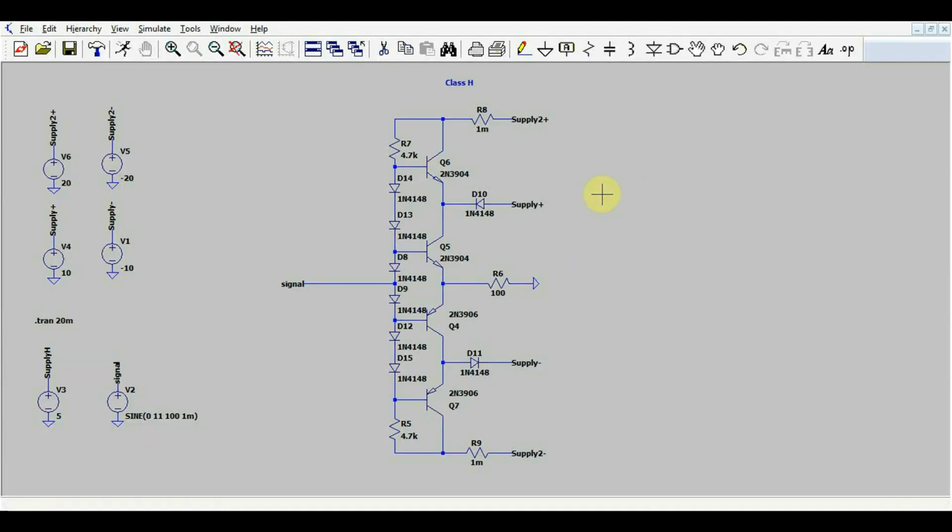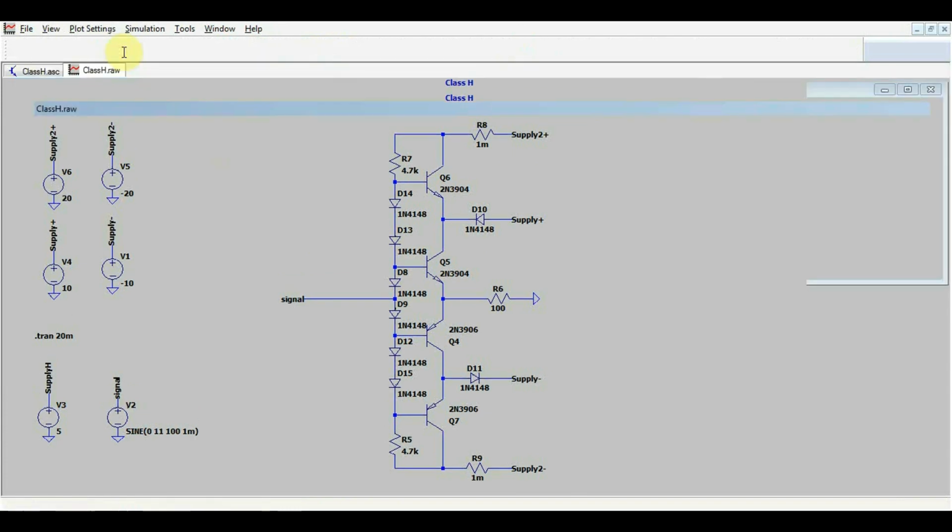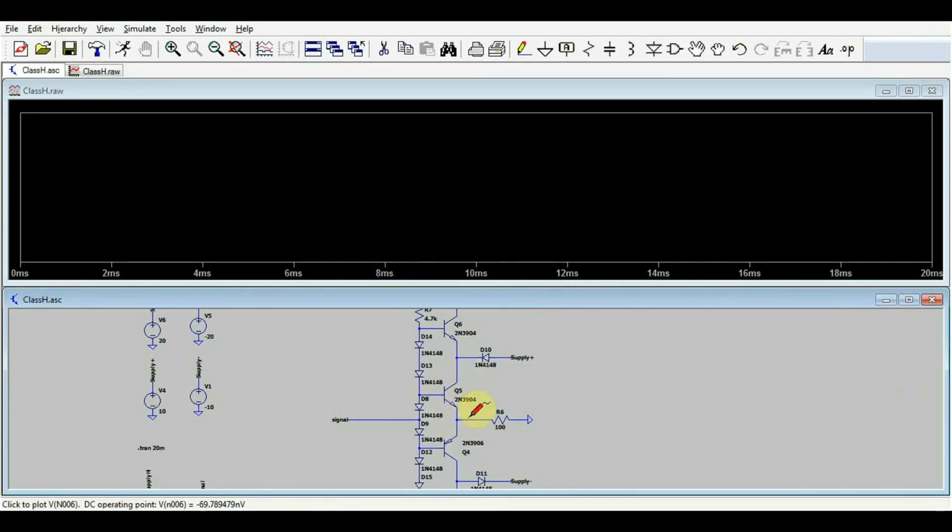So this is what this kind of amplifier looks like put into practice. We keep our base AB class amplifier in the middle, we have our initial supply voltage, and when our input signal reaches sufficient amount of amplitude, our secondary supply gets utilized. But because of the configuration we are using, the supply that goes into our output stage will only be the input signal plus a certain amount, so 0.7 in this case. So let's quickly look at how this thing is running.